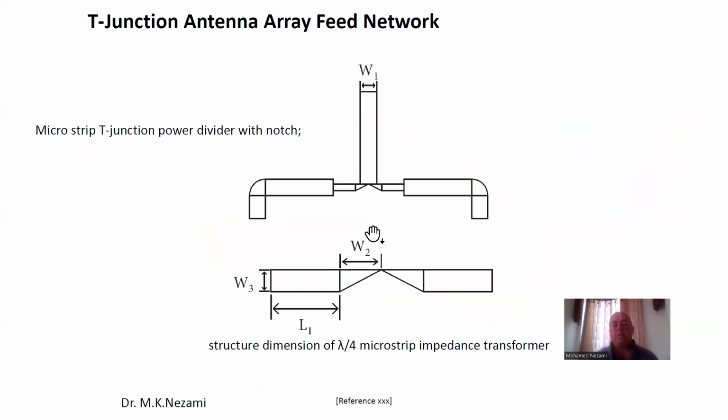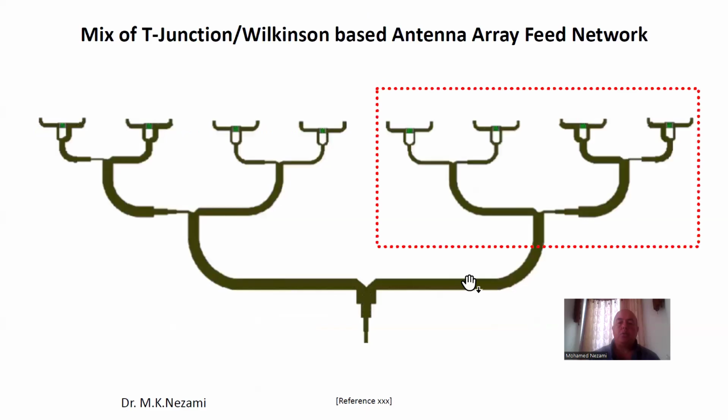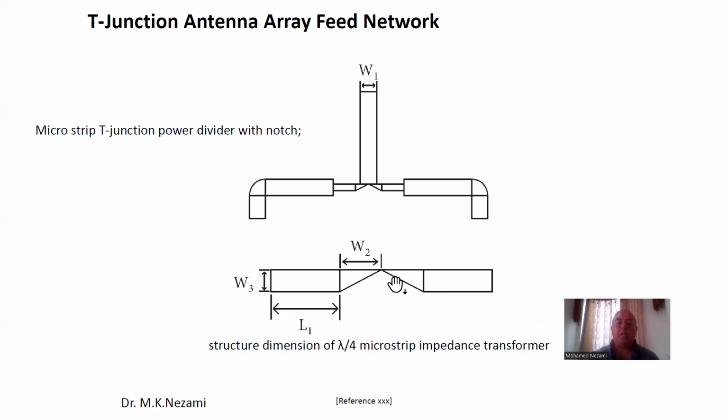Now, there's an addition to the T-junction that can improve the discontinuity, and this is well established in the references. You can see that a lot of times they have this little notch in here, because it turns out that most of the reflections are on this side here. You can see demonstrations of the T-junction in online movies on the distribution. You can see all the reflections in here. So they taper the middle with a triangle, and for this triangle in here, they have rules.